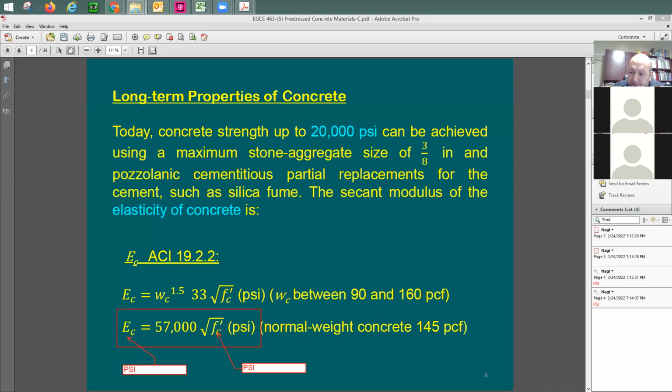research. If you are doing research, this is going to be very critical, and I have a hard time. In the past, like 25 years ago, I was doing testing in the structures lab, and we were trying to get to exactly 4,000 psi concrete, and that was a big deal, and it was very expensive because I didn't want 5,000. Every time, they would say, why don't you come to the batch plant and just pick the cylinders you want and do your testing?